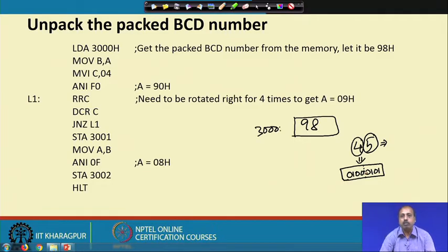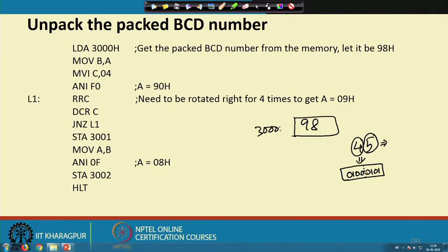So, instead of converting this into a binary number, we can store them in the binary coded decimal format, and this has several utilities, particularly while you are displaying some decimal digits onto some display. So, this format is often useful. Many times we store 2 BCD digits per memory location. Memory locations are generally byte organized, so per memory location we store 2 BCD digits, but in the application it may be required that we access each BCD digit individually.